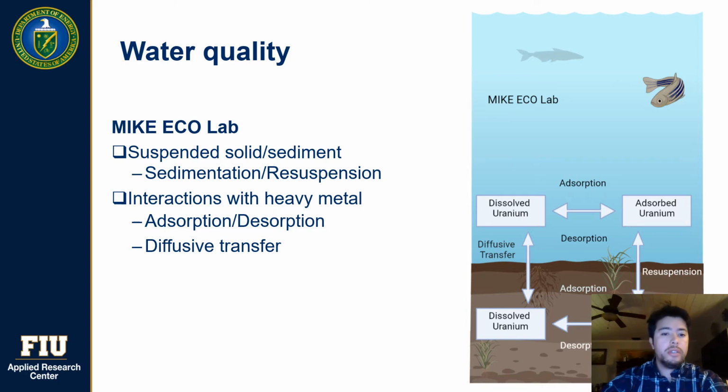After achieving a reliable hydrological model, we began building the model capacity to predict the metal transport. In this case, this was done by coupling MIKE 11 and the MIKE ECO Lab module. The ECO Lab module, as stated in the picture, simulates sediment transport through sedimentation and resuspension, as well as the interactions with heavy metals through adsorption, desorption, and diffusive transfers.